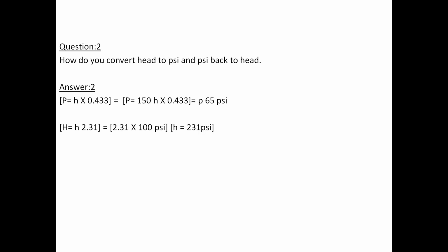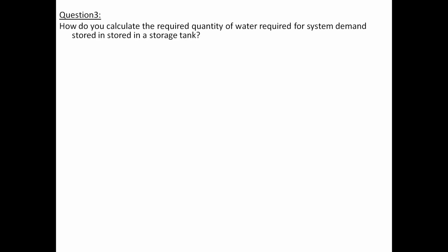Question number 2. How do you convert head to PSI and PSI back to head? PSI is equal to head times 0.433. Head is equal to PSI times 2.31.